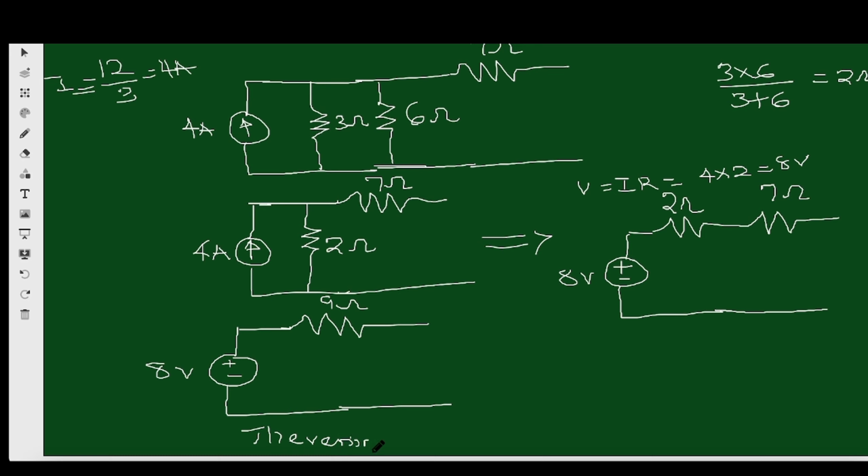So this is the Thevenin equivalent circuit. Remember, the Thevenin equivalent says that it is possible to replace a complex network with just a voltage source in series with a resistor, right? And this is what we have done to reduce that circuit to that. So this is just network A. So when we connect back our network B, which is a load resistor, what do we have? We have RL here. So this is the circuit. So of course we can get anything that is connected to this RL.